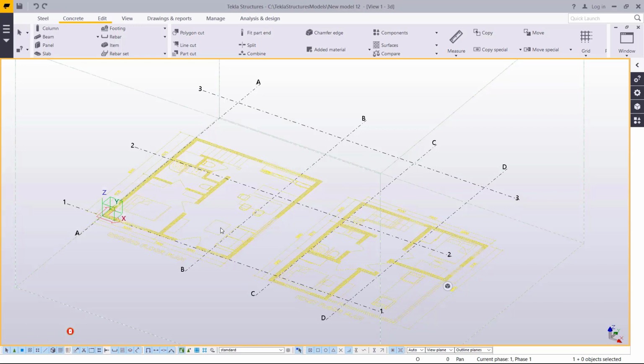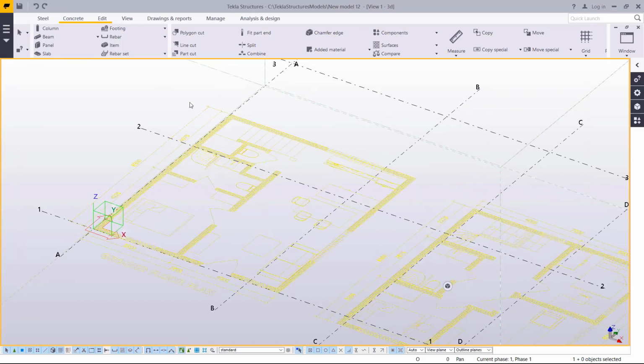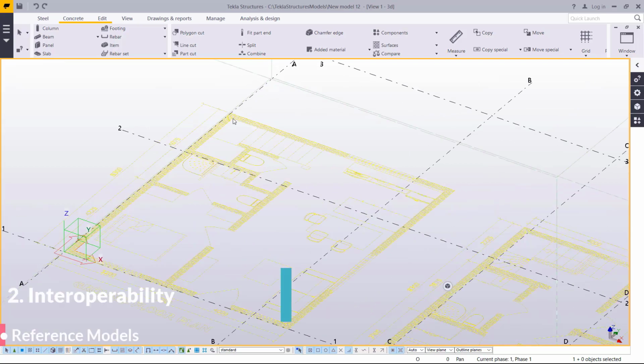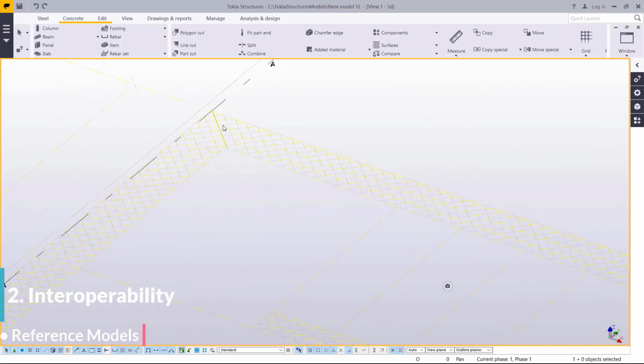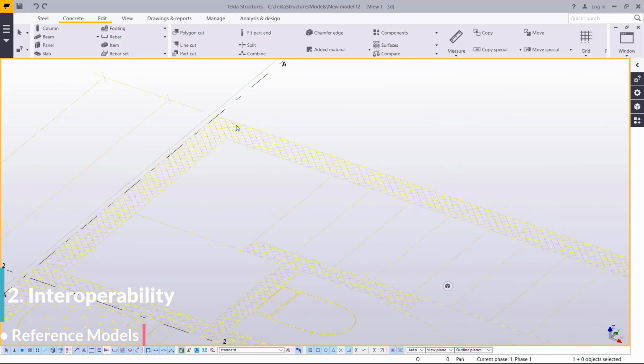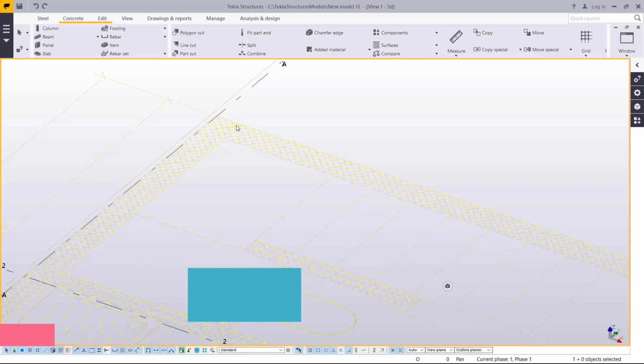Now we are going to pick this and develop our structural drawing right from here. But for the structural drawing, we will not do everything because of time, and I'm just showing you how you can interoperate between different software. Now, the plan we need is the ground plan, or the ground floor. So what we are going to do here is start by placing the pad footings, and then we move to columns, then we go to strip footings, all those.